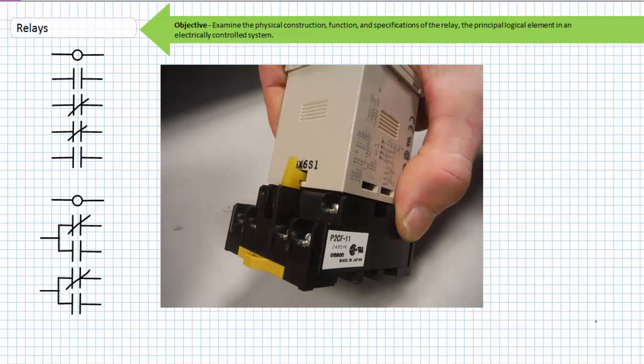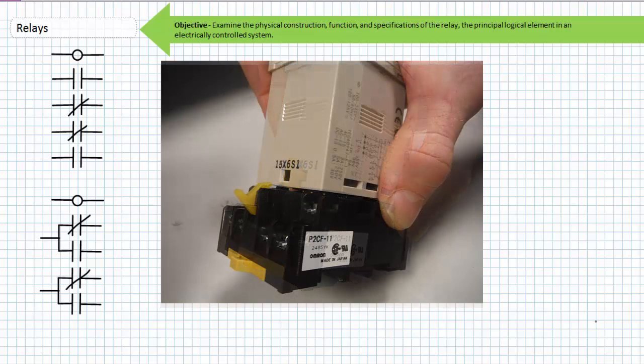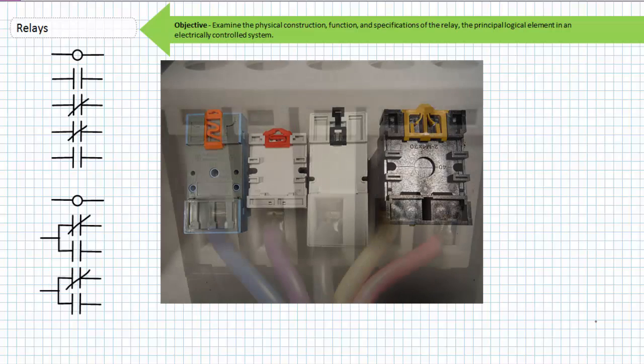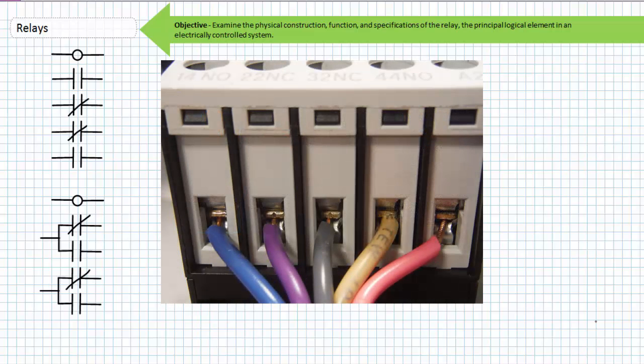Sometimes plastic hooks lock the relay into the base and must be unhooked for the relay to be removed. Don't be the guy that rips a plug-in relay out of its socket and hears broken plastic pegs tumble into the equipment you're working on. The back of the bases typically clip into a rail. In contrast, an industrial relay is typically directly hardwired into the system.